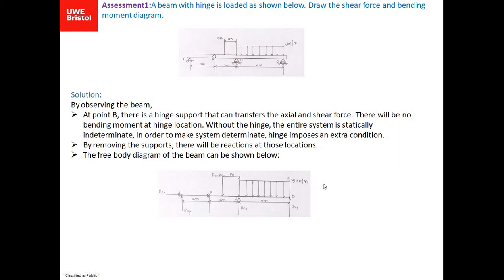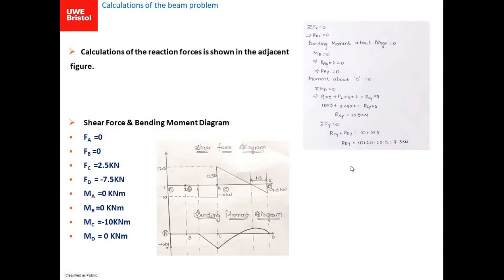And now coming to the calculations of the reaction forces, which can be shown in the adjacent figure. Here I considered sigma Fx equal to 0. It means I consider the equilibrium condition in the x direction as well as the y direction, and by taking moments about particular locations, we can determine all the reaction forces.